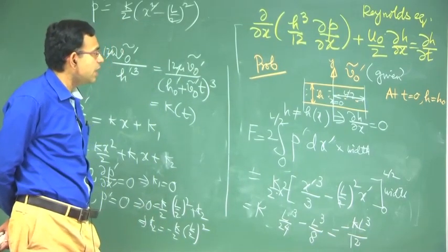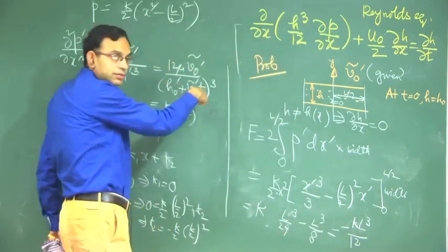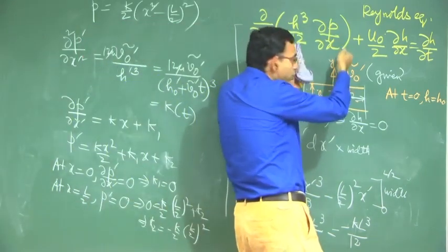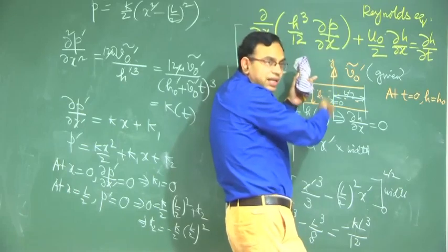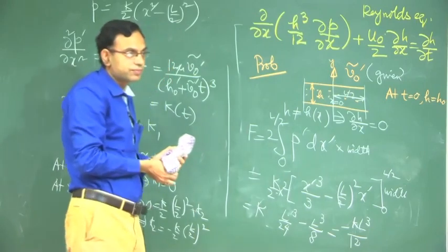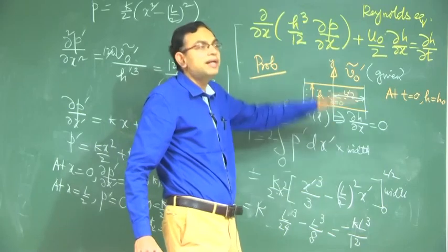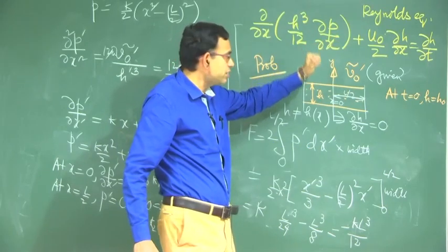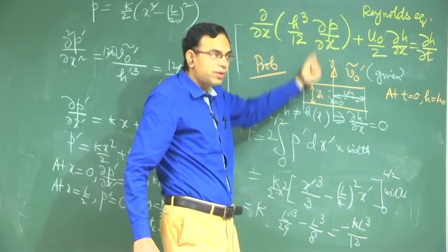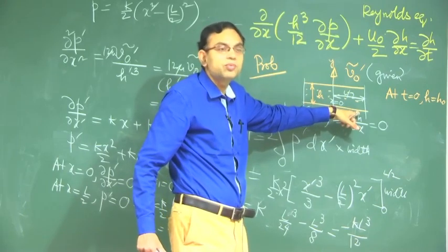So, one interesting thing is that we can see that the force is negative because this is all positive, right. Force is negative means when the plate is moving up there is something which is actually dragging it down, that is the physical meaning of this negative force. Now, in this way can you calculate the force unlimitedly? You cannot, because when this plate goes up and up and up there will be a situation when this H becomes comparable with L and then lubrication theory is no more valid.